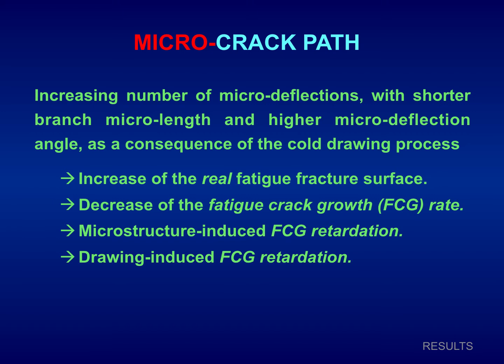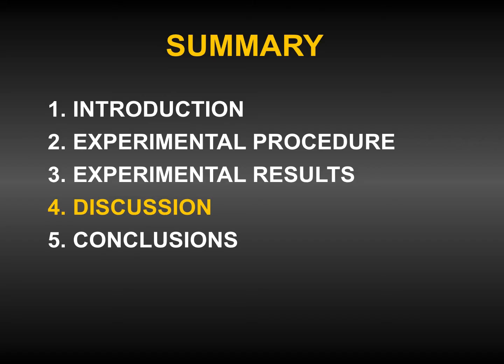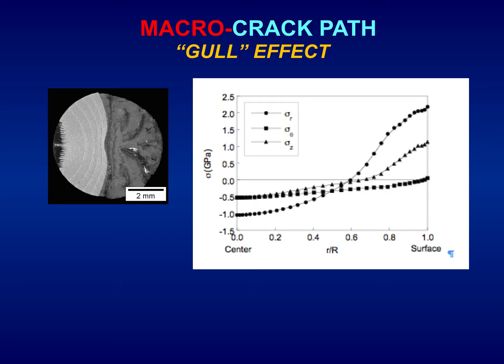This has four effects. 1, increase of the real fatigue fracture surface. 2, decrease of the fatigue crack growth FCG rate. Third, microstructure-induced fatigue crack growth retardation. And lastly, 4, drawing-induced fatigue crack growth retardation. Let's go to the fourth part, discussion of the results.